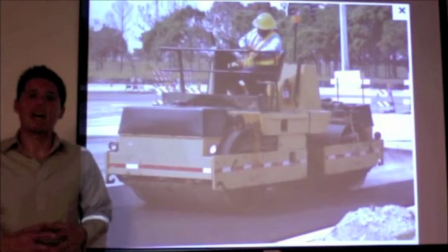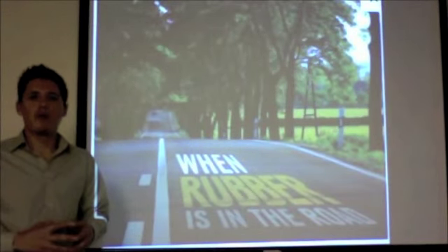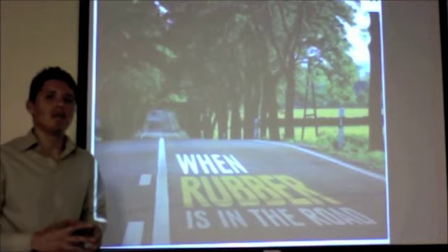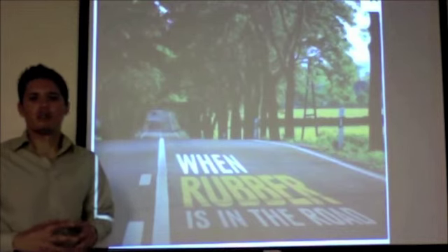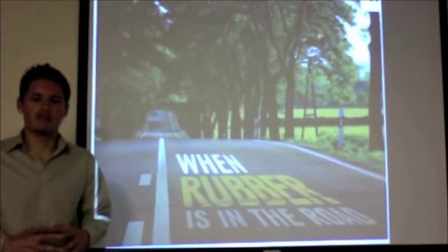Pavements should be designed with a traffic index of 7. The asphalt section should consist of rubberized asphalt over 2 inches aggregate base over properly prepared subgrade. The subgrade soil should be proof rolled prior to placing the asphalt section and compacted to 95%.